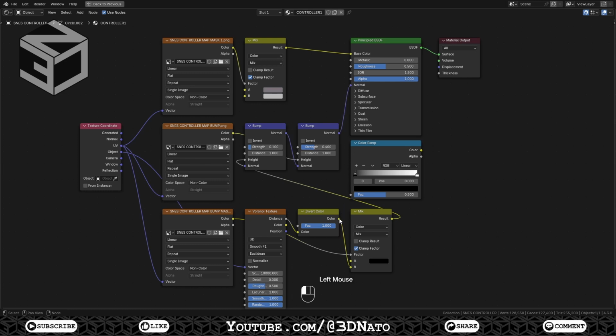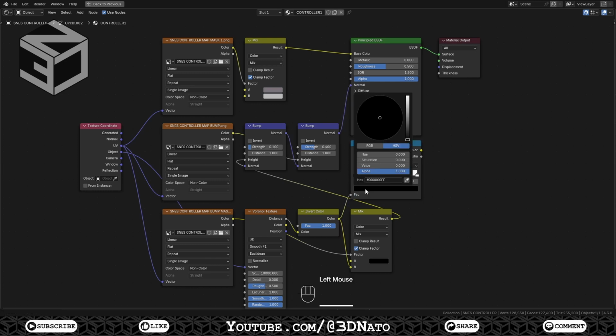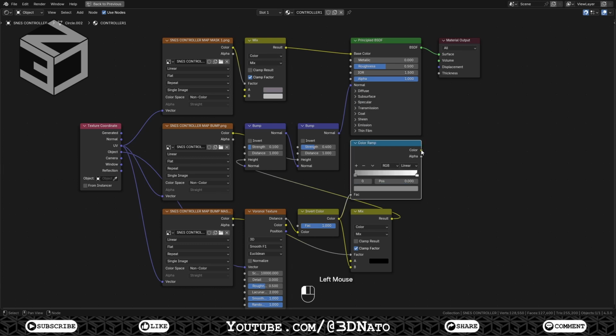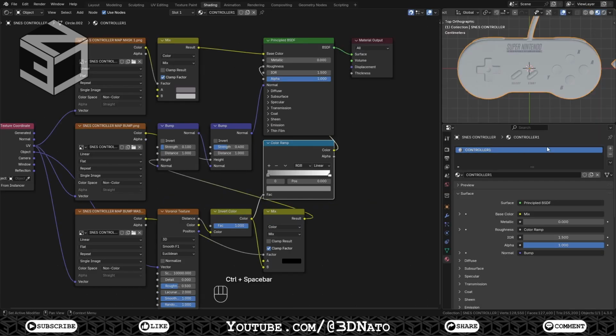Connect the invert color to the color ramp fac and set the black color value to 0.25 to make it gray, and connect the color ramp to the principal shader's roughness. The roughness controls the amount of specular reflection, where a value of 0 or black will give a perfectly sharp reflection, while 1 or white gives a diffuse reflection. Setting the Voronoi texture colors to go from white to gray will prevent parts of the mesh from having mirror-like reflections.